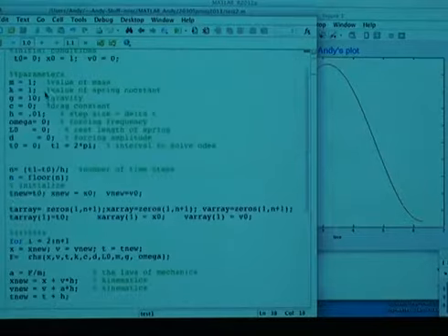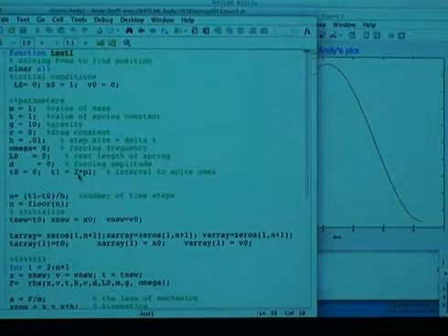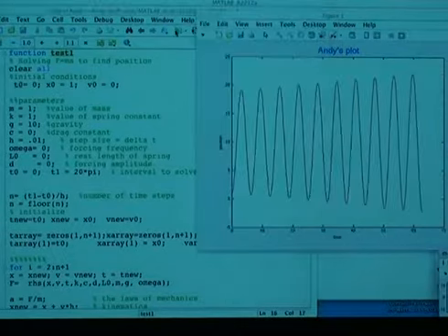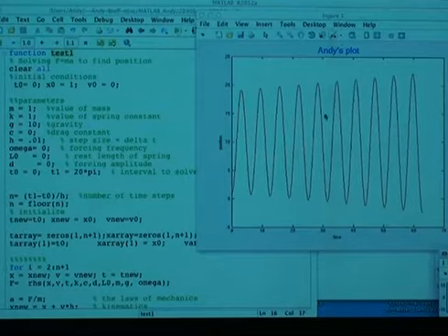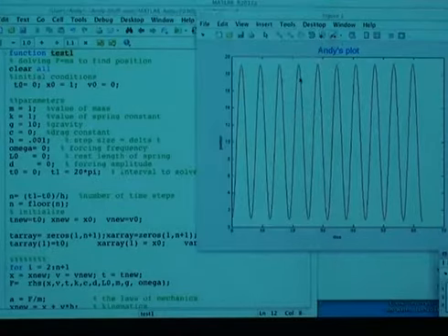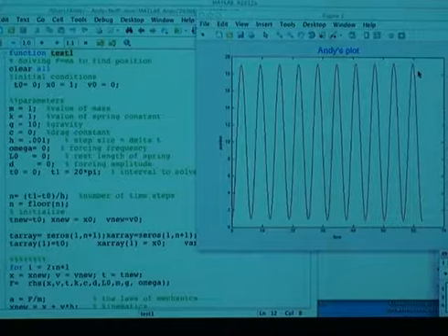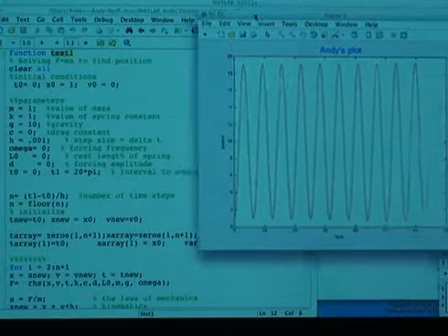So let's do something. Let's run this thing for a longer time. So let's run it for 20 pi. And now we can see the effect of these different parameters. Okay, 20 pi is not being so accurate. So we're seeing this growth in amplitude, which is not a real growth in amplitude. So let's get this accurate enough so that we can see the effect of things. So now there's a little bit of growth of amplitude. It looks like a kind of negative damping, and that's a numerical error. So let's just pretend this is constant because I don't want to wait all day for the solutions.